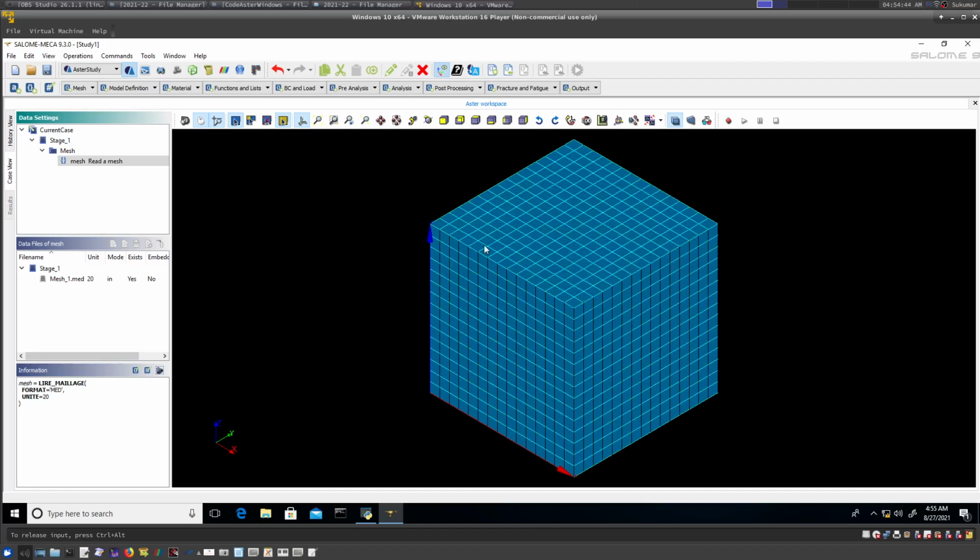Okay, so while meshing it, the direction of the surface may be towards inside also. It is basically obtained by cross product of these two vectors. Say this surface will be obtained by the cross product of these two vectors. Now depending on the node numbering, these two vectors may be in this direction and the other may be in this direction.